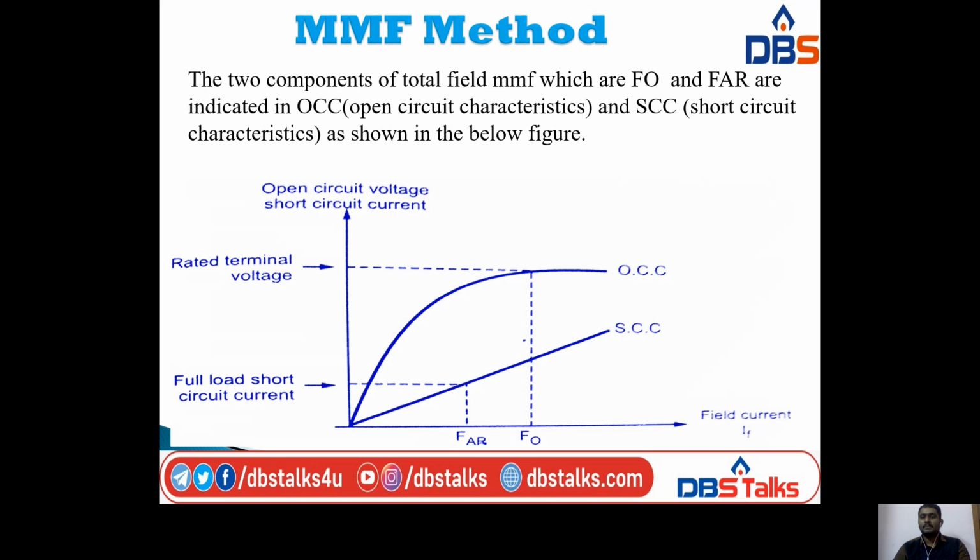And next, the two components of total field MMF, which are F0 and FAR, are indicated in the OCC curve, that is open circuit characteristics, and the SCC curve as shown below. So this is the characteristic diagram for the MMF method for both cases, open circuit and short circuit test. Here the open circuit characteristic is drawn between open circuit voltage and field current, and the short circuit curve is drawn between the field current and short circuit current.